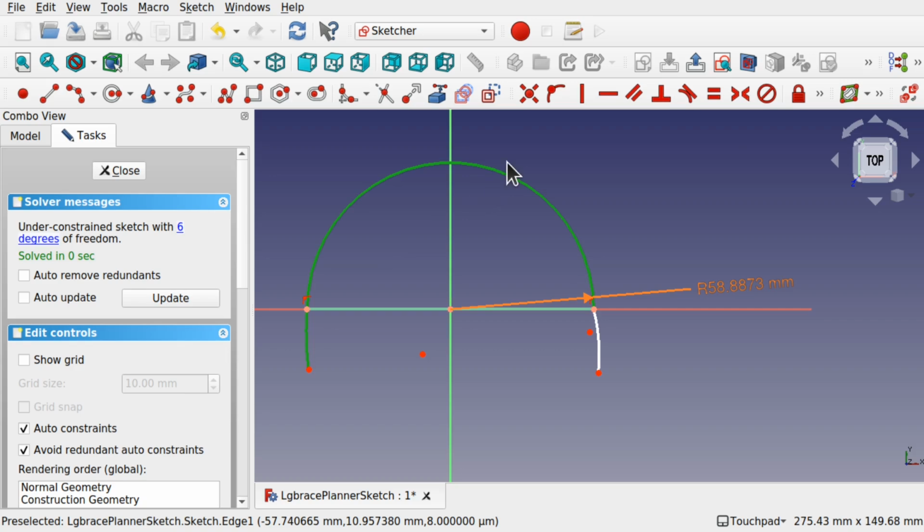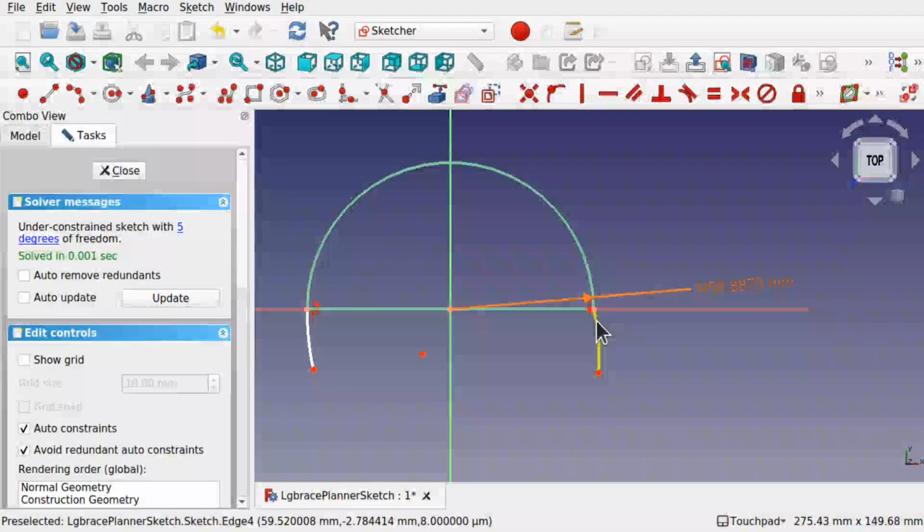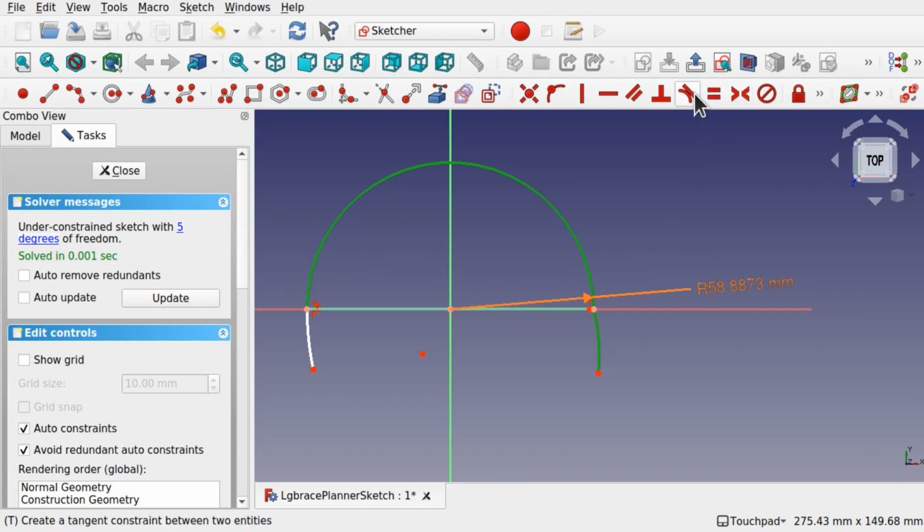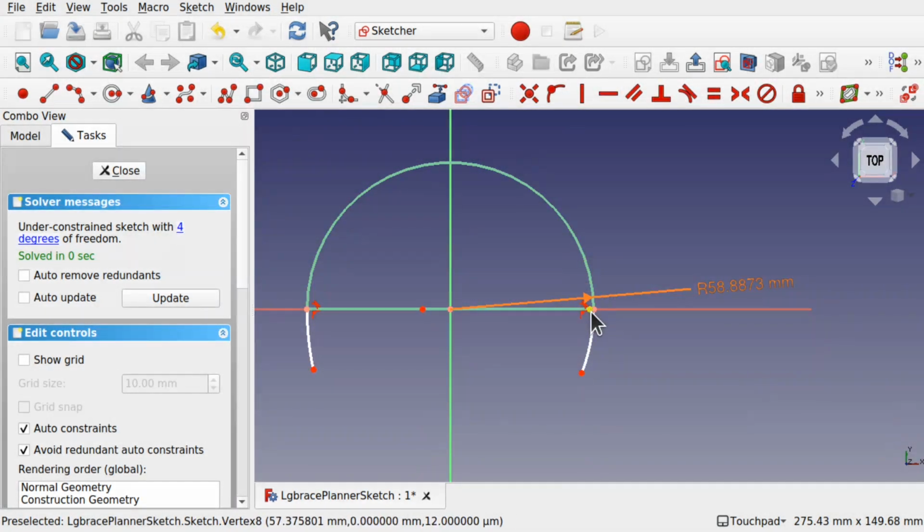And we'll make tangency across here, okay, and tangency across this one as well. Okay. We've got this here, which is this arc, and this one is this arc. You can see those moving. So we need a line that goes across here, connects those up. Now let's pull this out so it's almost straight, and the same this side, and set the height.